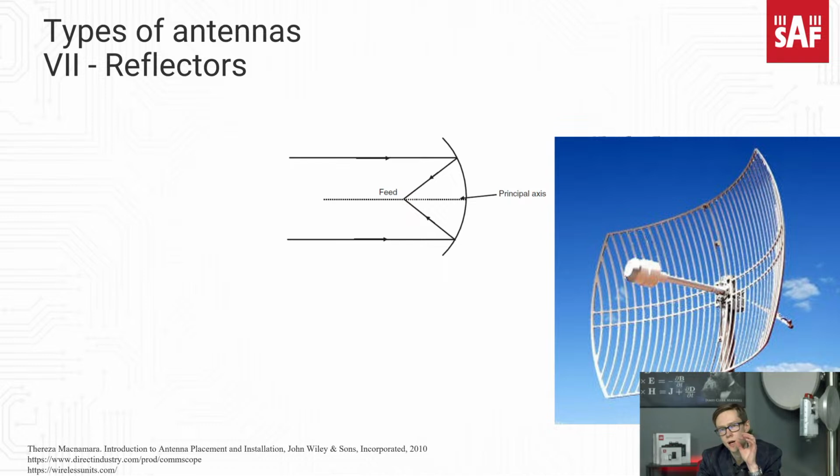This is used for some lower frequency ranges, and we can get rid of the solid reflector and substitute it with this grid reflector, because this grid is reflective for the lower frequencies. For the lower frequencies, the wavelength becomes larger, and this grid is able to reflect such a wavelength, just as the solid reflector could reflect the higher frequency waves.